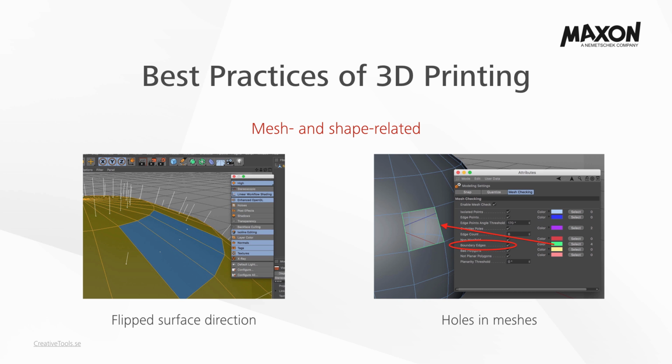Another common error is the occurrence of holes in a mesh. For 3D printing, it's important that a mesh is watertight and has no boundary edges. An easy way to check your object for holes is to activate the modeling mode in the attribute window. Then choose a tab called Mesh Checking and select Boundary Edges. This will highlight any holes in your meshes, and then you can proceed to close them with your standard modeling tools. The reason why it's important to avoid mesh errors is that the slicing software will not understand the geometry of your object correctly, and this can lead to failed prints.